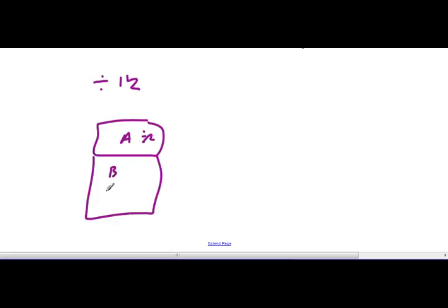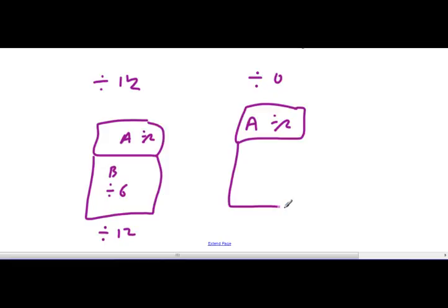So we look at the divide by 12 guy. What we get is 2 counters. We get an A counter, which is a divide by 2, and we get a B counter, which is a divide by 6. And if I hook them together, if I took the output of A and put it into B, then I'd have a divide by 12. In the divide by 10 counter, the decade counter, we have 2 counters. We have an A counter, which is a divide by 2, and then we have a B counter, that's a divide by 5.